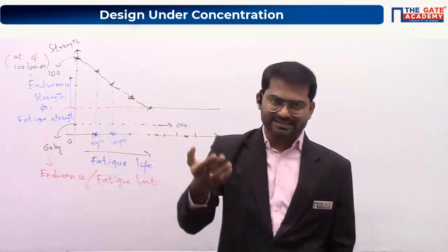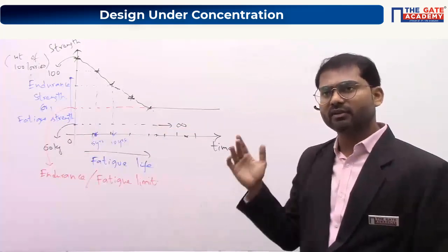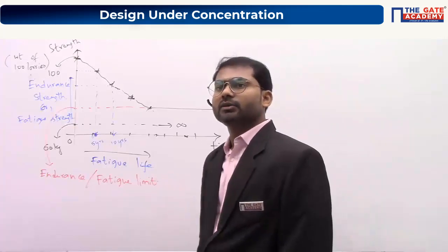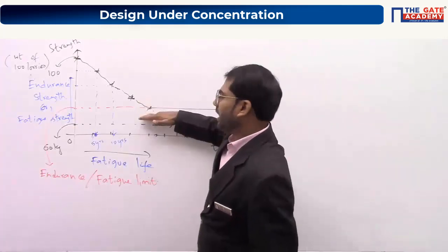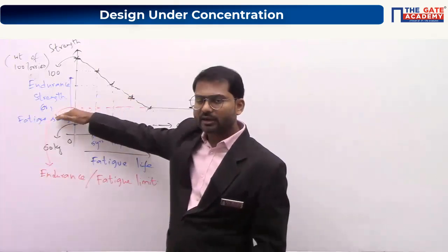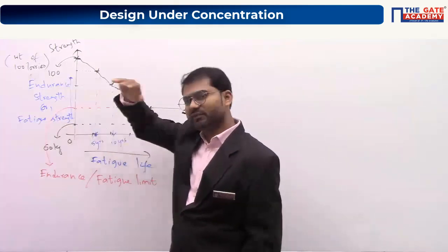So if the stress value is less than that value, the component will have infinite life. That's it. Clear now? Understood? If it is below this value, it will never fail. If it is above this value, that means the stress induced is more than this endurance limit, it will definitely fail.